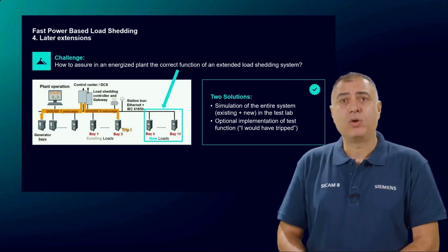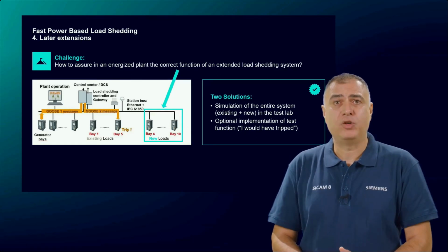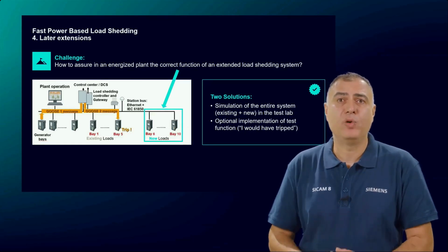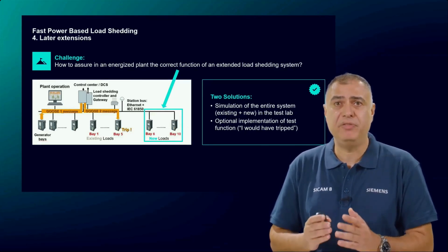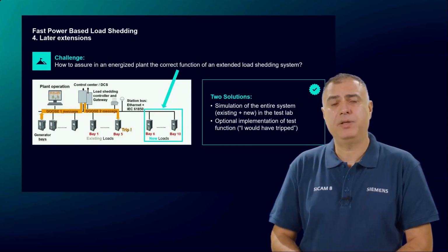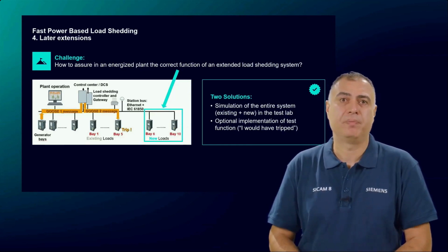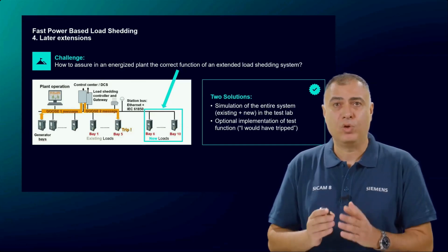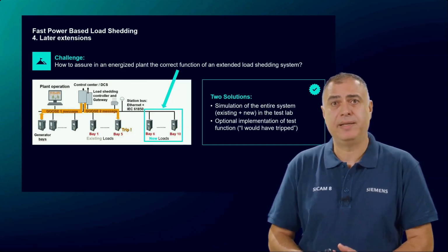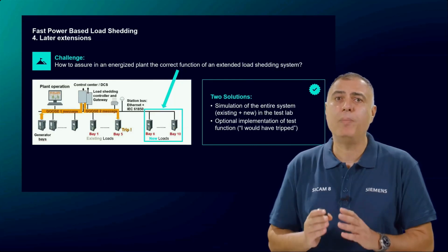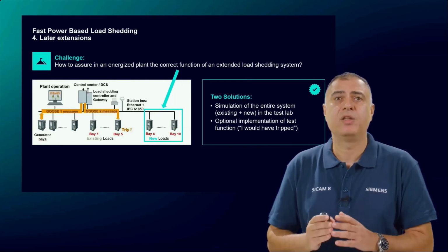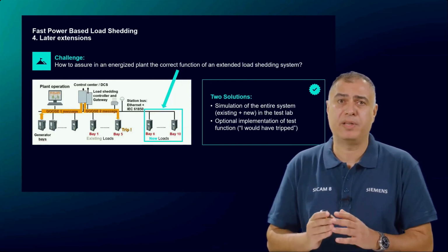By selecting a contingency feeder at the HMI, the operator can simulate the trip of a contingency feeder. This information is sent to the corresponding contingency relays. The contingency relay treats this simulated trip like a normal trip and starts the standard load shedding process.